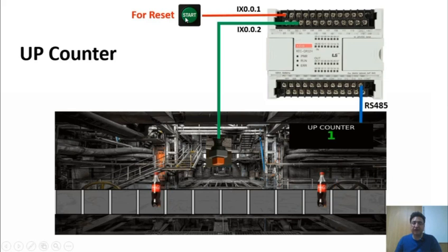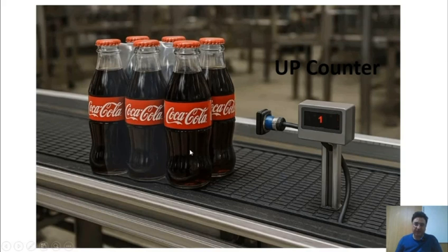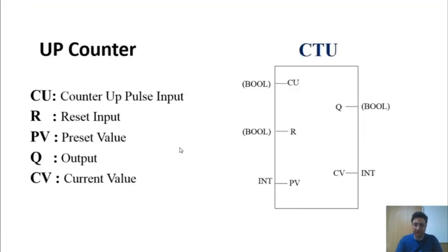Whenever we press the reset button, the entire counter value immediately goes back to 0. Now, we can count these individual soda bottles, and then, at a later, more convenient time, we can pack them all together as a single pack. Here, we can use another sensor again, and we can also count the number of these completed packs using this same sensor and the counter that we use within the program itself.